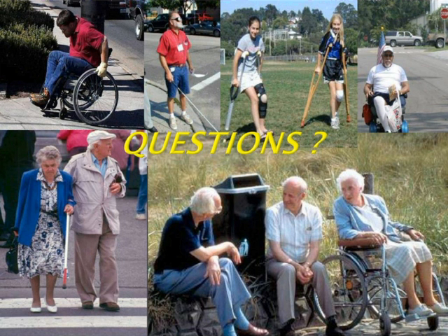The 2% really was always cross slope. On the tiles themselves, that might be what you're thinking about, people ask, does the 2% apply to the tiles too? And that would be yes. And that's why I say with the cast iron and the stainless steel, when you're stepping on those things, be careful, and check that it's not more than 2%. The detectable warning should follow the longitudinal and cross slope of the ramp.